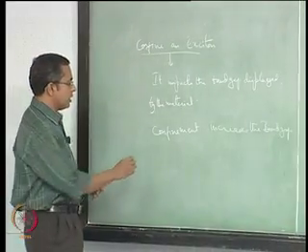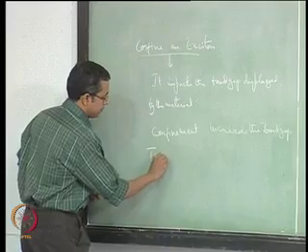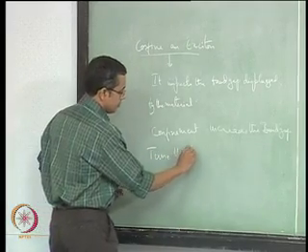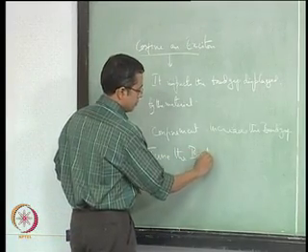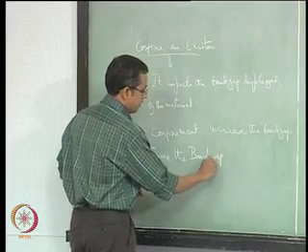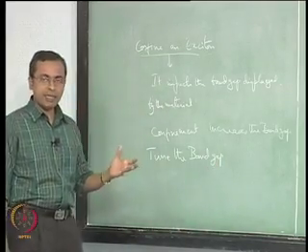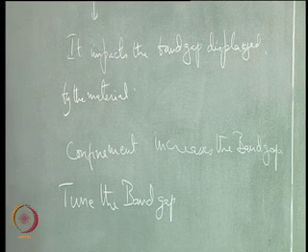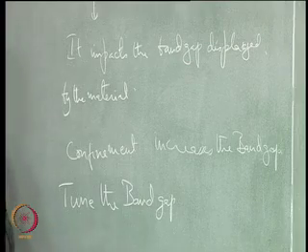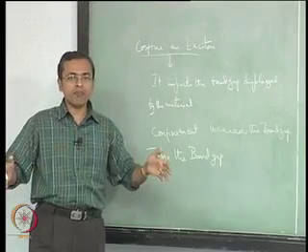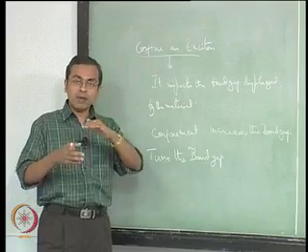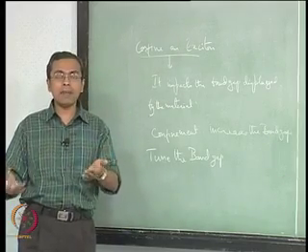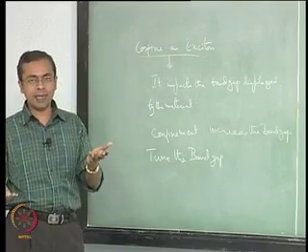What is more important is you can actually tune the band gap. If you do this carefully enough you can get a collection of particles of roughly the same size, all near the exciton Bohr radius dimension, and since they are essentially the same size, they will all have more or less the same band gap, but it will be different from the bulk band gap.